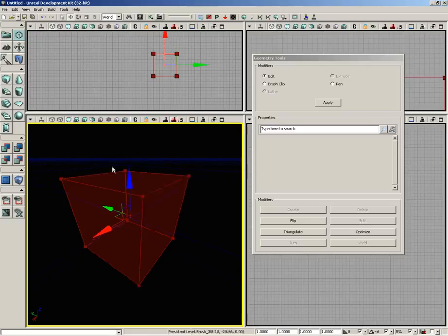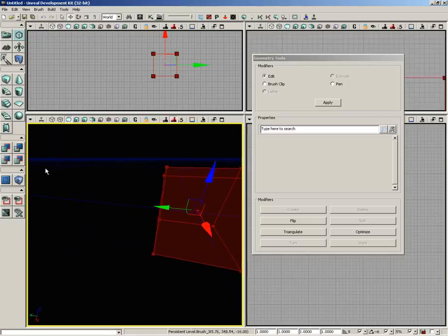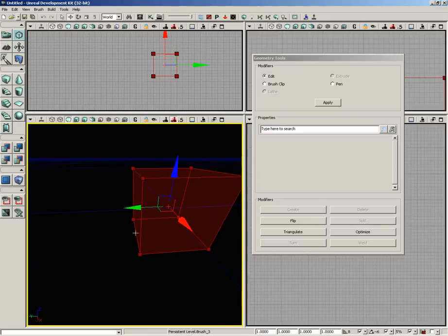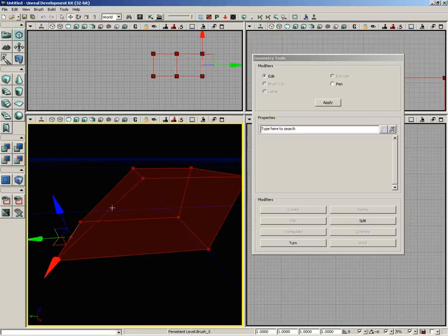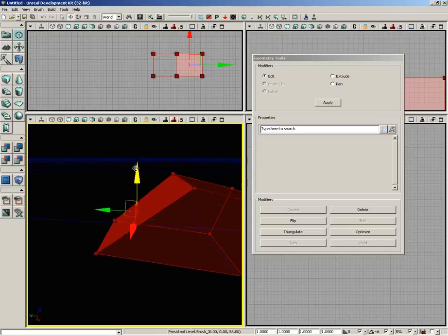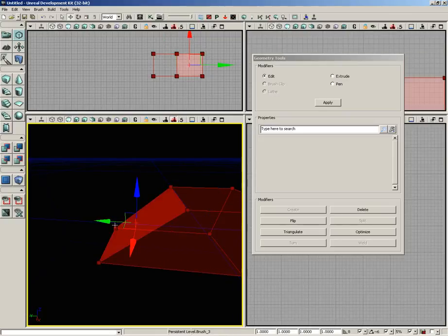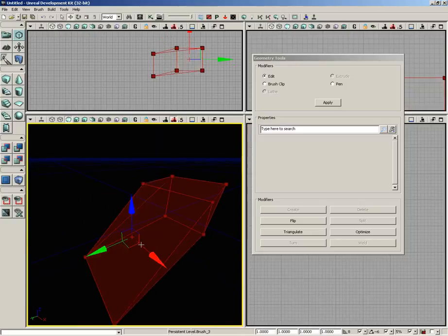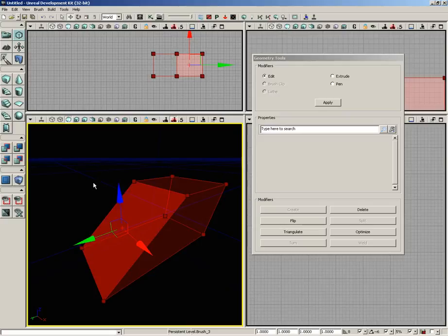The other thing I wanted to mention is that you can make use of your reference coordinate systems to get some interesting motion. If I grab this edge down here on the lower left-hand side of my box and we slide it out, now I'm going to grab this polygon face. Now take a look at my translation widget. Currently its axes are aligned to the world axes. We can move up in Z, we can move forward in Y. Now I am tapping undo in between these to reset everything. And we can move side to side in X. But those are based on world coordinates.